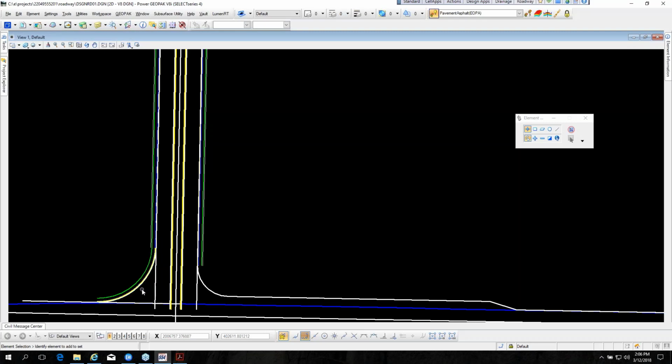So that kind of makes sense. I mean, civil cells can be tricky, but once you get to know how they're built and how to use them, they seem a lot easier. So now with that civil cell, does everybody have the sidewalk placed off of that first curve? Because now we're going to go ahead and, on exercise 3.12, create a custom civil cell, or custom curb and sidewalk lines, so we can make that easier to place for the other sides.